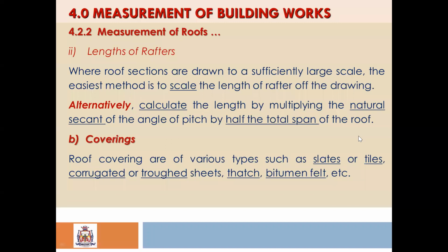But I'm saying that if you are sure of the scale, that is when you scale off from the drawing. Otherwise, you'll use the various mathematical calculations. How? We can calculate the length by multiplying the natural secant of the angle of pitch by half the total span of the roof. This goes to the usual calculation of triangles, trigonometry, and others may come in.